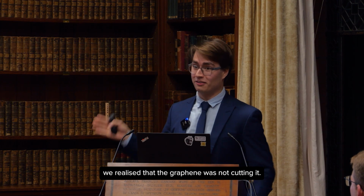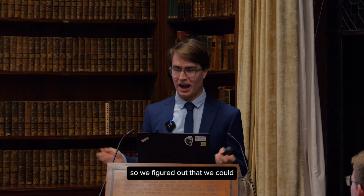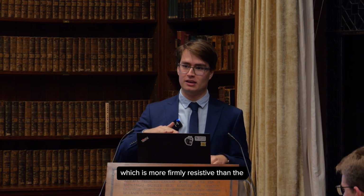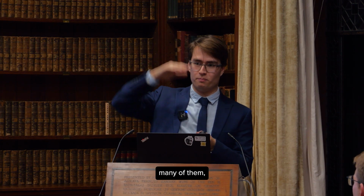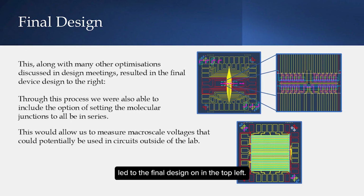But in doing so, we realized that the graphene was not cutting it. It did not provide the necessary heat flow to get to the junction. So we figured out that we could potentially etch under, as in dig a hole under the graphene to create an air gap, which is more thermally resistive than the material that it was originally under, along with using, instead of a single layer of graphene, many of them, about 6 of them, to ensure a more proper heat flow. This, along with many other optimizations, led to the final design in the top left.